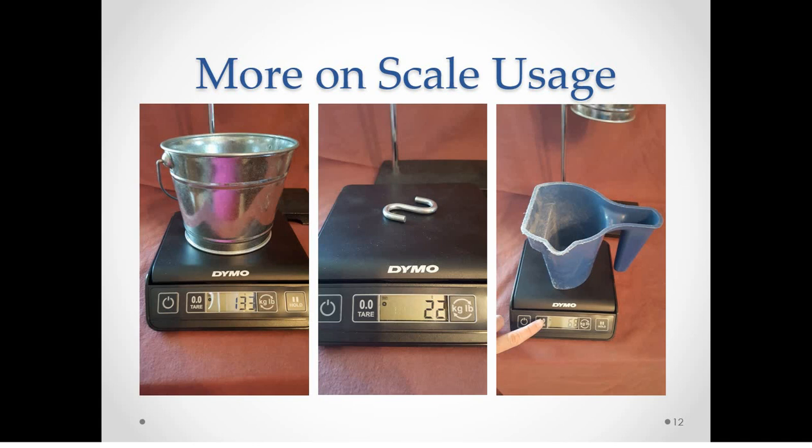They will be measured in the blue plastic scoop. Therefore, the scoop is placed on the scale and the 0 tare button is pressed. That means that the mass of the rocks to be added to the bucket will be measured without adding the mass of the scoop to the mass of the rocks.